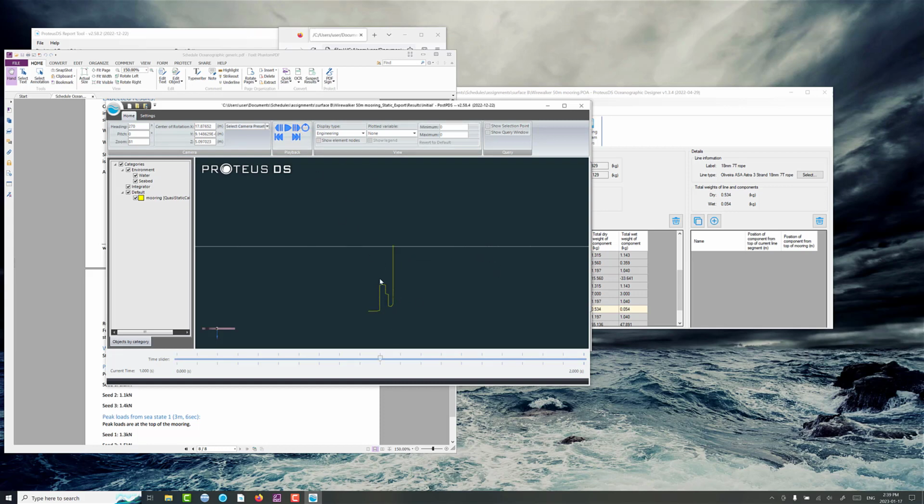It's a pretty low tension mooring in this region, so it might look a little stepped, but it's just because it's very, very low tension through this region. There's the chain. The profiling line comes down to about here where the weight is. And then it gets stretched out a little bit with the relatively minimal current profile. So this is what it looks like under that relatively mild current profile. And we're going to want to use this for the start of our dynamic runs.